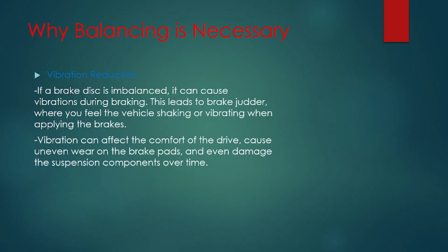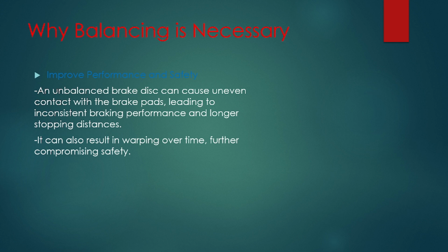Necessary. Vibration reduction. If a brake disc is imbalanced, it can cause vibrations during braking. This leads to brake judder, where you feel the vehicle shaking or vibrating when applying the brakes. Vibration can affect the comfort of the drive, cause uneven wear on the brake pads, and even damage the suspension components over time.